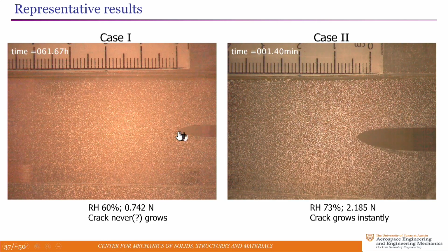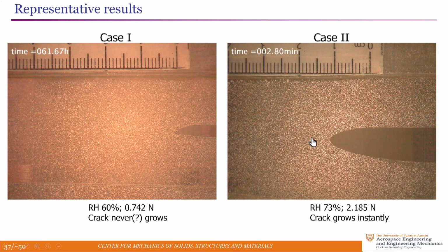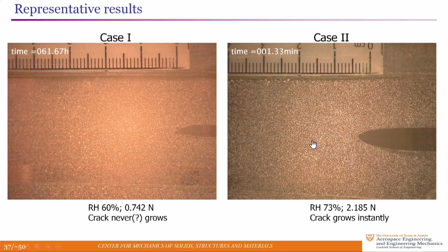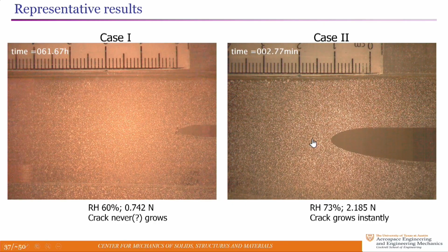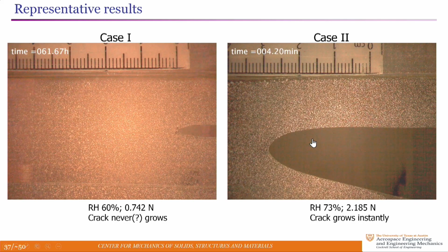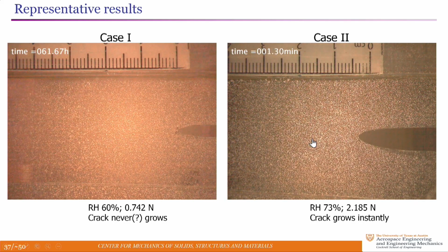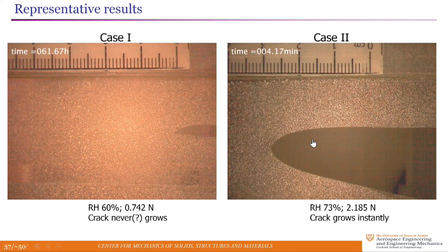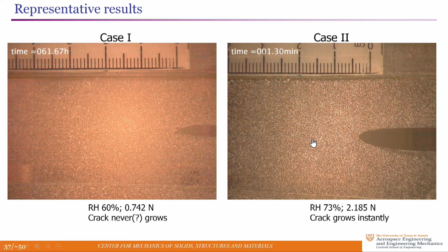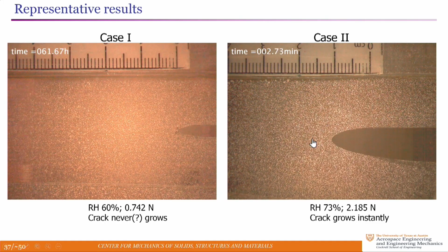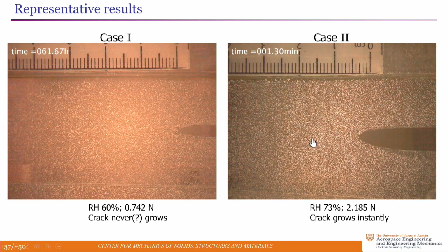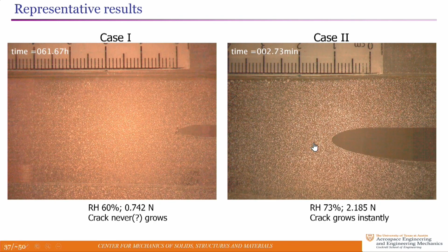One, there's no cracking whatsoever, and here there's instantaneous response. The instantaneous response would indicate that the poroelastic effects are going to be minor, because you remember the time scale for diffusion was on the order of hours or days, and in a matter of 2 minutes, it's not going to diffuse the water anywhere. It can create forces because the water is in a non-equilibrium state, but it's not going to create any energy there.